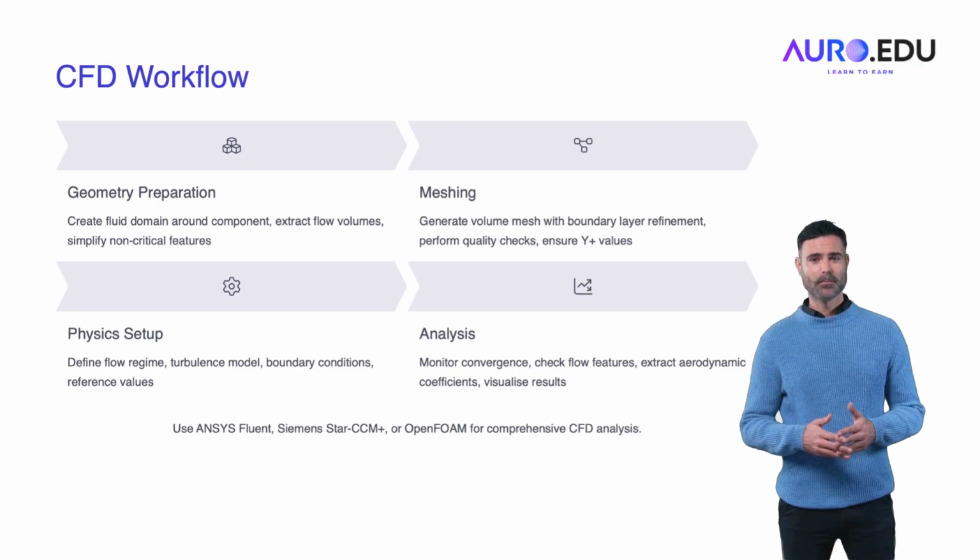CFD workflow. Prepare your geometry by creating a flow domain and simplifying non-critical details. Meshing is more complex, especially near boundaries and surfaces. Then, set up the physics, flow type, turbulence model, and boundary conditions. Finally, run simulations, interpret flow patterns, and extract coefficients like lift and drag. CFD helps make your design more aerodynamic and efficient.